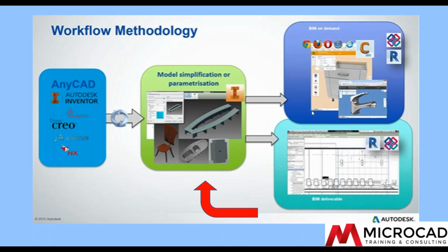With Inventor, that's easy. Inventor can link the Revit model into the Inventor product design and let the designer work with the architect's geometry. Because it's an associative link, if the Revit model changes, the Inventor model changes also. And this is a closed loop. Your updated Inventor model can become a Revit family, which can update the family in the architect's BIM model. This way, everybody sees the most recent data.